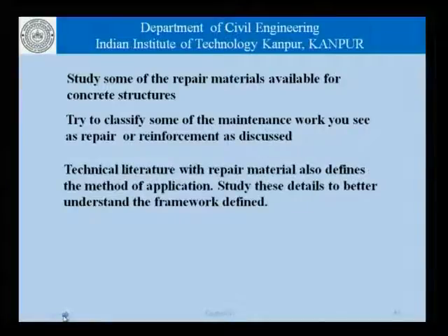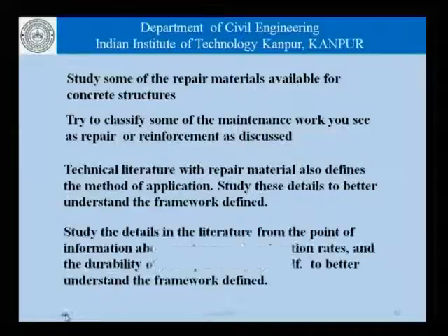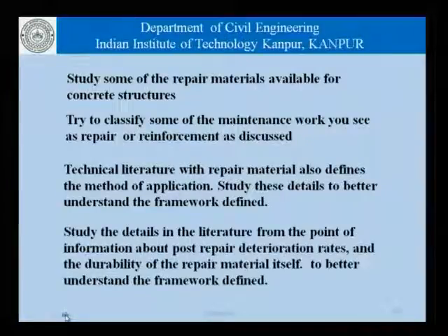Technical literature with repair material also defines the method of application. We could study these details to better understand the framework defined in terms of a combination of the material and the method. Study the details in the literature from the point of view about post-repair deterioration rates and the durability of the repair material itself to better understand the framework defined.